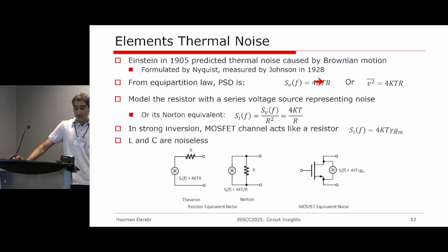The power spectral density turned out to be roughly a constant. It changes with frequency a bit, but for the most part, it's frequency independent. It's a function of k, the Boltzmann constant, and T, temperature. Certainly, that's where the randomness and agitation comes from. Of course, it is linearly proportional to the resistor. If you take an integration over a certain bandwidth, let's say 1 hertz, you can convert this from energy to power, so we can use these interchangeably to characterize the noise.